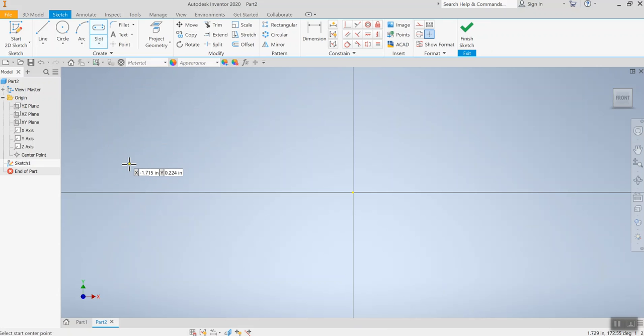In this case, I will select the first center, then the second center, then I will give the diameter of an arc. So the overall length will be whatever length I have selected plus one time radius here and one time radius of an arc at the other end. The total comes as the diameter of a circle, whatever we have selected.